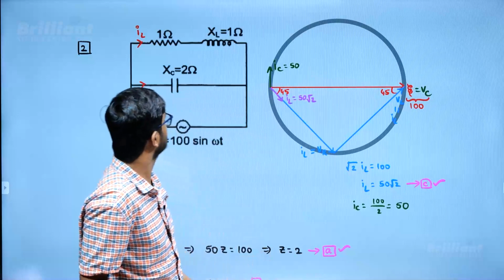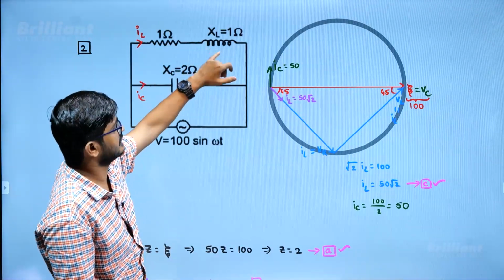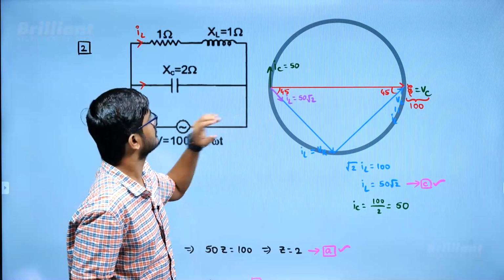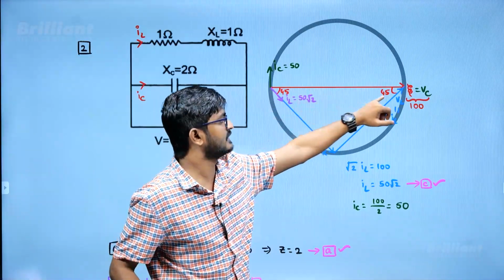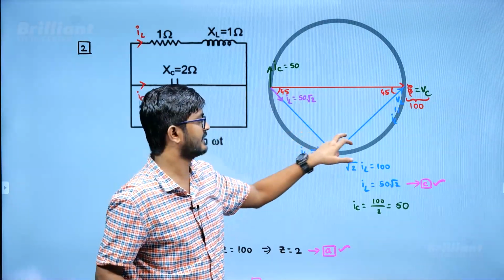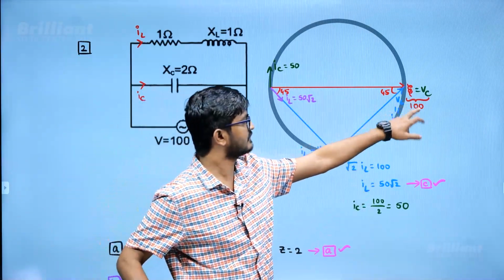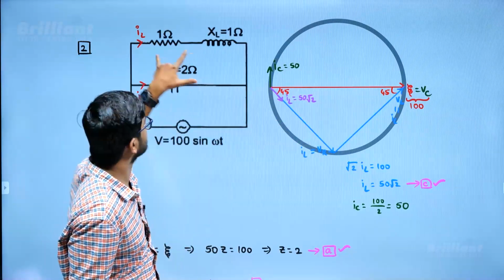And what about the thing? The thing is, both are of equal resistance, right? So resistance and inductive reactance, these two must be of same length. So from there I can conclude this angle is 45 degrees, this angle is 45 degrees. It will be making a 90 degrees here, right? Yeah, source voltage is 100. Okay, that is fine. Now, what about V across resistor?